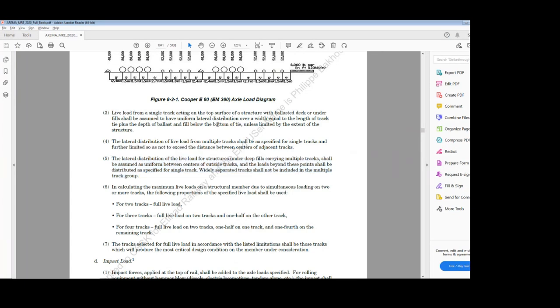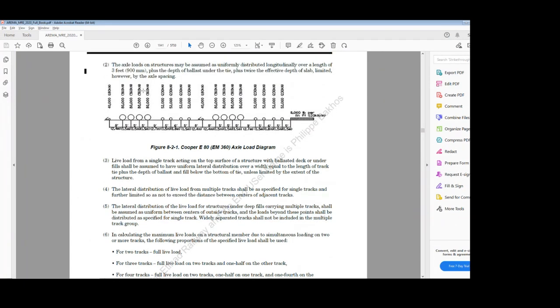I'm telling you again. For a bridge type structure in which there is an expansion gap, not necessarily every type, there are also structures where the depth of fill is 0 meter, then you have to use moving load analysis. So basically you have to use an influence line diagram there. In that case, you need not disperse this live load. You have to apply it as a point load, and for structures having fill depth, you have to apply this live load as a pressure load.